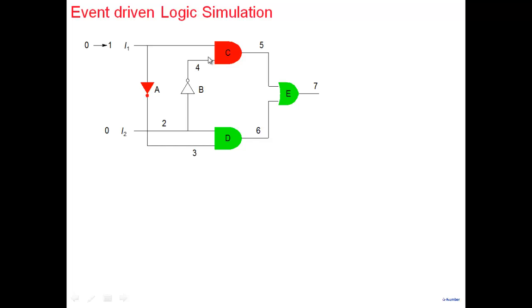If we keep on doing it in a systematic manner, we end up simulating the circuit in an efficient manner, in the sense that for each input vector, instead of simulating all the n gates, we may end up simulating only a small fraction of the gates. We also saw that, the way the algorithm works, you may end up simulating one gate more than once, but it doesn't really matter because the number of gates simulated is small.